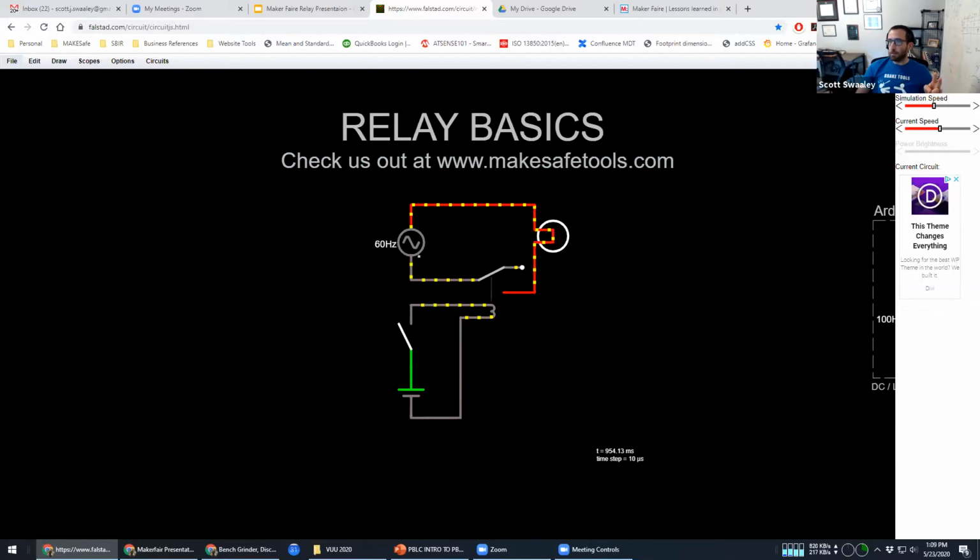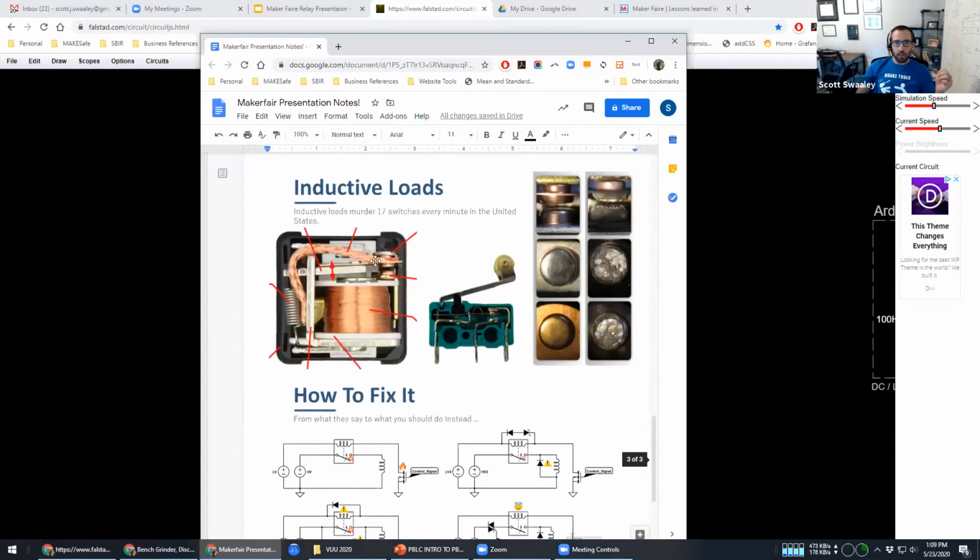One is, and I'm going to drag another screen in here just to show some pictures. A relay, like most switches, is literally two pieces of metal that touch together to make electrical contact, right? That's the fundamental component, like in this cross section of a relay. The only difference is instead of you pressing that, it is brought together by a big electromagnet. So that project you did in high school where you wrap wire around a nail and it becomes a magnet, that's all this is. And so by activating this electromagnet, it turns on that switch. So that's what a relay is fundamentally.